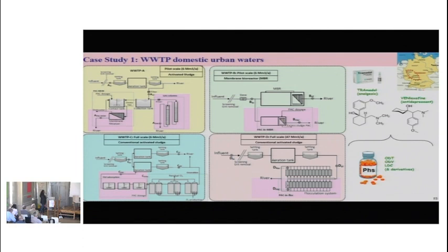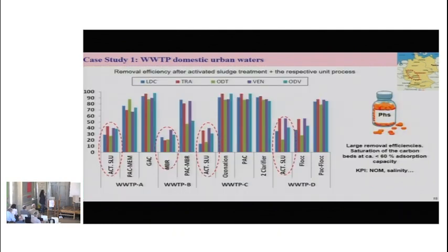We also have some ozonation and some flocculation systems with different configurations. In this case, we were targeting these 2 compounds, an analgesic and an antidepressant, because they were the main pollutants detected at the outlet of the wastewater treatment plant, and some others that I cannot disclose.